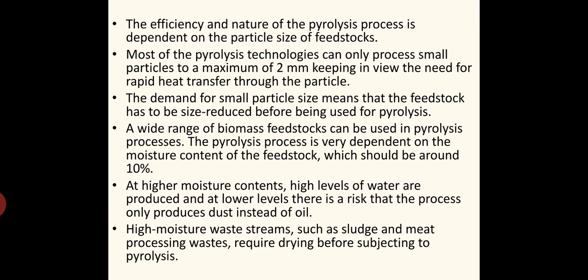We are heating the biomass or the organic materials at a rapid rate, at a high temperature, and heat transfer should also take place within a short period of time. So in order to assure that, the surface area is to be increased for the maximum heat transfer. The size of the feedstock, that is the biomass that we give, should be minimum, around 2 mm in size. 2 mm means very small size.